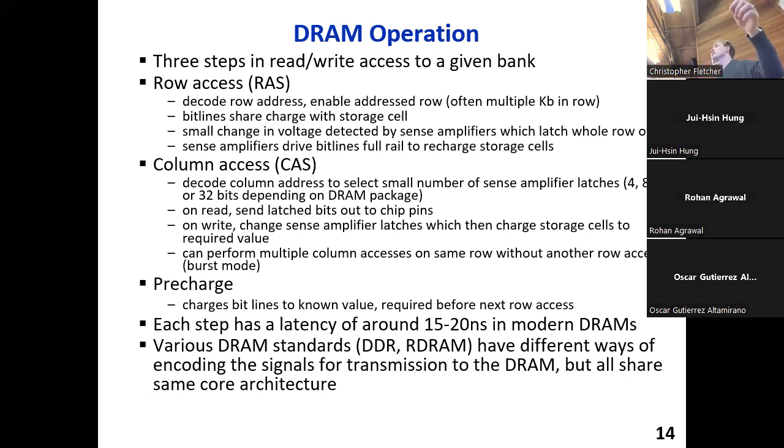And so what pre-charge does is clean it out so that when you open the next row, any residual charge there on the bit lines does not interfere with the values on the capacitors in the newly opened row. So it's kind of like a way of resetting the system. If you want to use the bucket analogy, when you dump the bucket out, you want to make sure that you dump it out onto dry ground. You don't want it to be damp ground, which could interfere with the amount of water that you dump out.